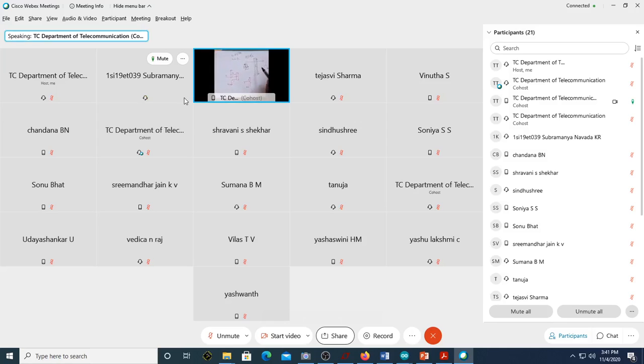Yes, sir. As per my program, once it becomes high-low, the motor will run in a particular direction for 5 seconds, irrespective of the condition. Yes, sir. Then of course, before 5 seconds, it will become low. Then the motor will not operate. Meaning, if it has opened, the door is still in open condition.